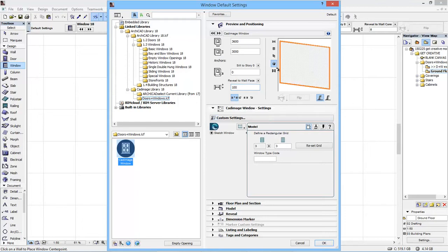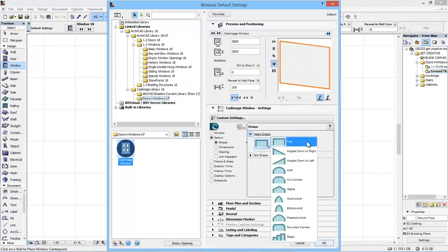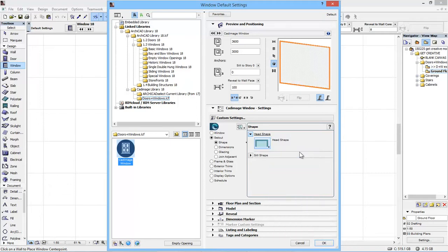So that's pretty much how the sketch sets out the window. You can set a few other basic things like the surfaces. At this stage, I'm not too bothered as long as I've got a nice big window. That's all I'm looking for. So really what I need to do now is go to detail design and then start to play with it. So let's start with the shape. Now the shape, we can define the top and the bottom. So we had a slope in that previous one. Let's just have a slope in this one as well. Once we pick it, we can then set various aspects of it. So I'll just have a drop of 600. If we know the angle, maybe we'll have a drop of 15 degrees.